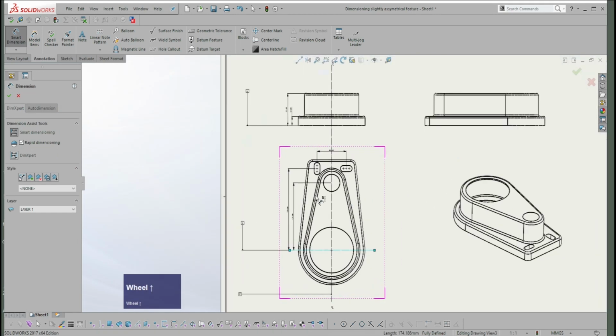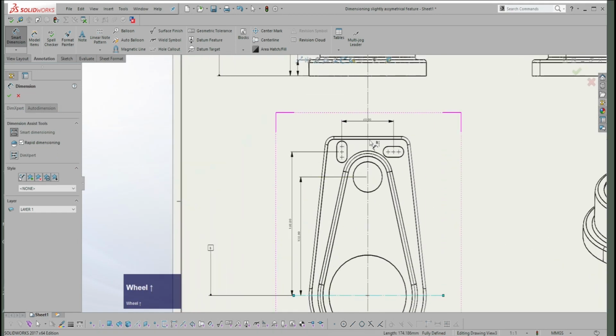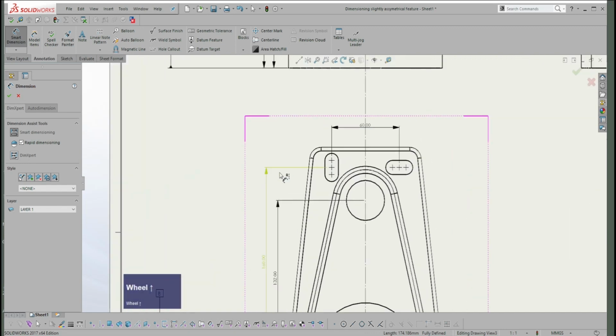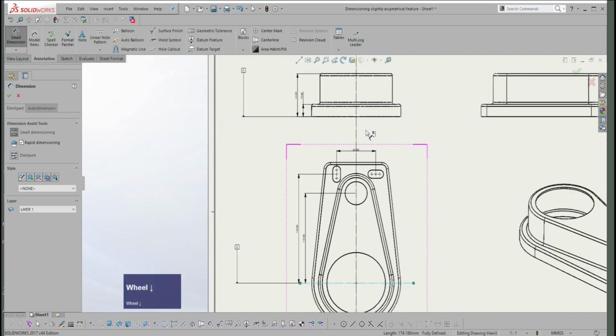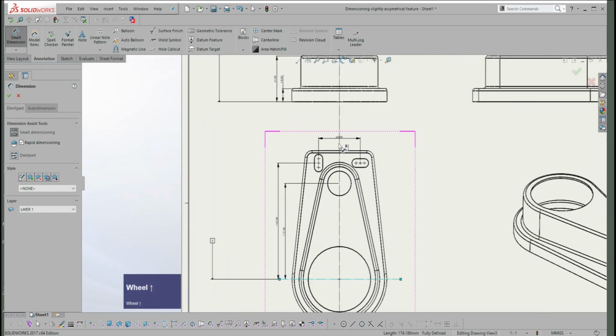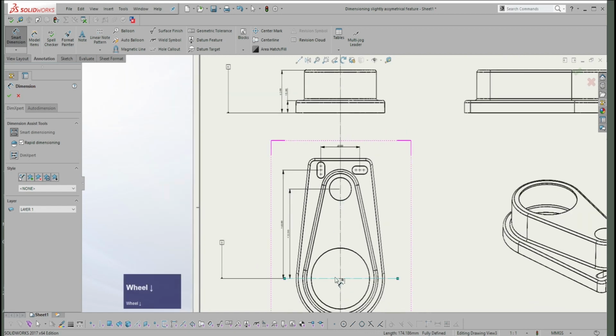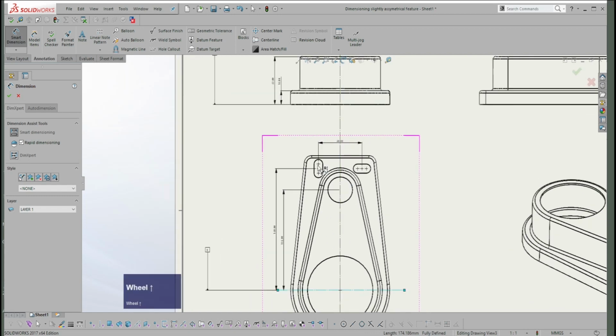Okay. This is really puzzling why it says this is already in place, because it isn't. But that's just to give you an idea. So I'm going from the datum. I want to reinforce this over and over. I want you to understand you always dimension the position of things from the datum. So here I have 2 positions for these slots. I've got the 60, that's the distance from the center line. That means that'll be divided equally by 2. And I've got the position from this datum to this circle and to those.